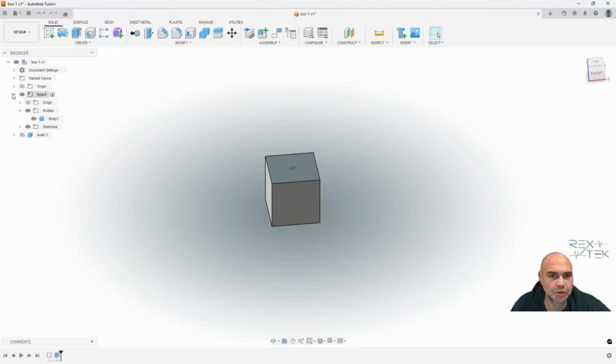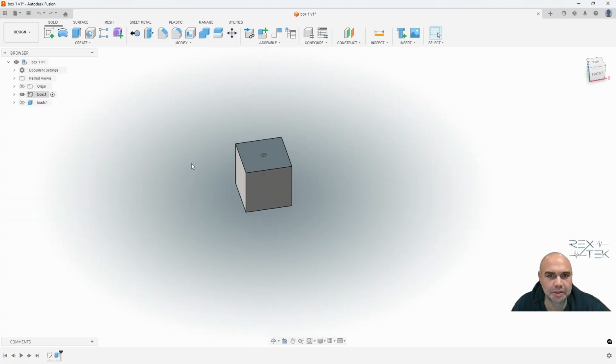Okay, now we're going to talk about components and how important they are. If you're just creating a single model and you're going to machine it without adding in any work holding or fixturing, or it's not a part of an assembly that you need modelled all together, it's not really important, but if you do any of those things, you need everything laid out in components. So the main thing about that is it's like having an extra folder that everything to that component or body is held together in one place.